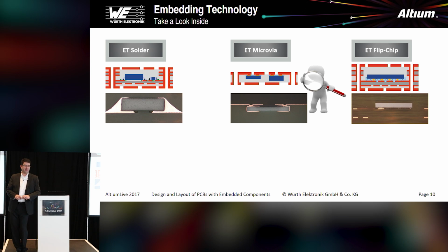So how does it actually look? This is always really interesting, and especially for the two on the left side, the solder technology and the microvia technology, I compared 0402 resistors. It's the same size, and what you already see here is the solder fillet. You do not have this one here, so this is space being saved.